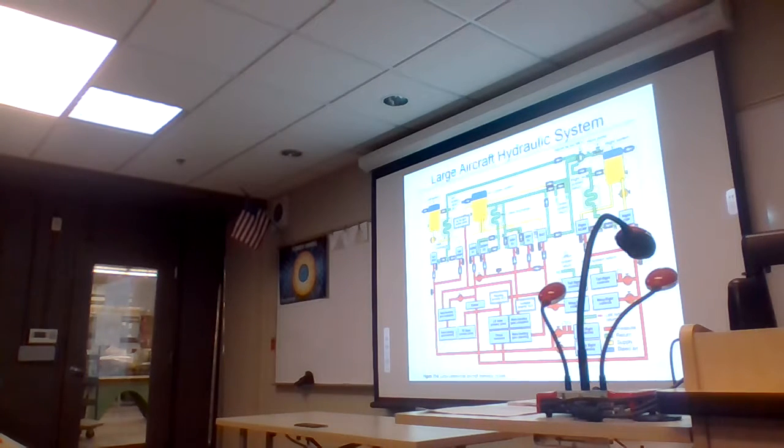It's interesting when you look at the hierarchy, or at least the distribution, of hydraulic fluid, how every different manufacturer has done things differently. This would be typical of a Boeing aircraft. You'll notice they've got what appear to be a couple of check valves that go into the reservoirs. On many of the Boeing aircraft, they pressurize the reservoir with air, bleed air. It reduces it in pressure, and that provides the push on the hydraulic fluid to prevent cavitation of the pumps.